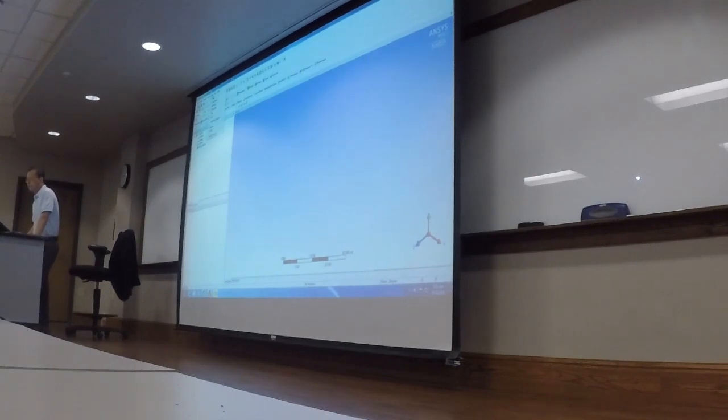Units, inch. YZ plane. Click on that. That's the YZ plane. Then go up here. We'll create a new plane. New plane. That's plane 4. And come here, let's change the transform 1 of global offset global x. Offset global x, -4.